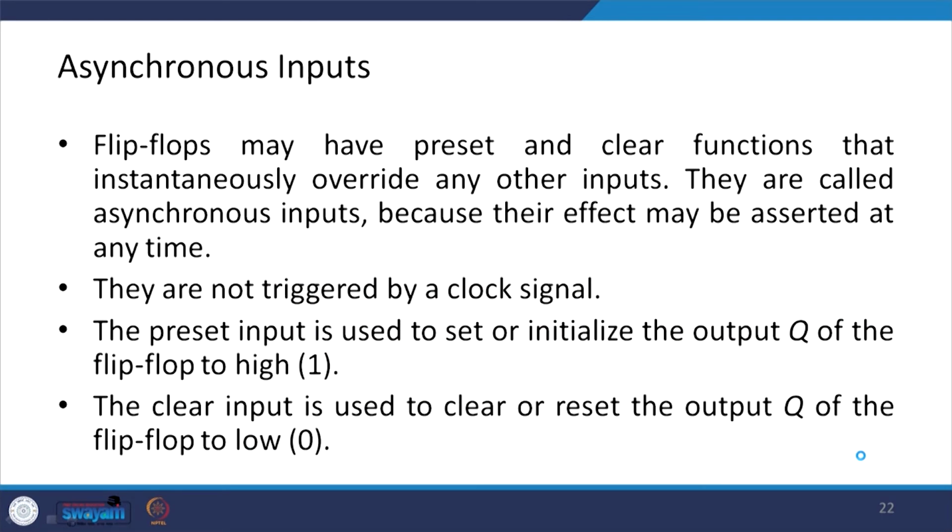Next, let us look at asynchronous inputs, that is, inputs which are not clocked. Flip flops may have preset and clear functions that instantaneously override any other input.